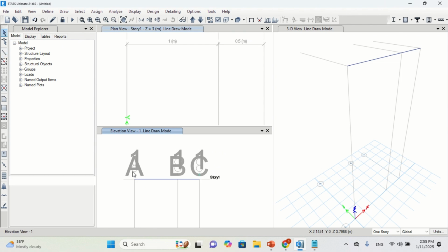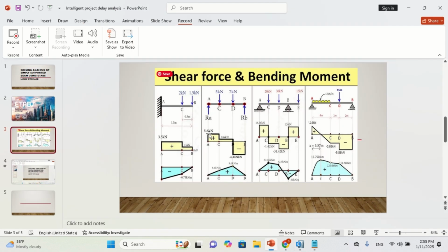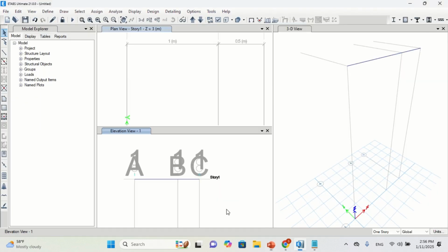The other thing that we have to do is you apply the restraint at this point. We have a one fixed support here. The next step is to apply the restraint. So our restraint is just one, and it is fixed beam. So we will apply. We'll first select this node, the grid point A, and then we'll go to assign, joint, and restraints.